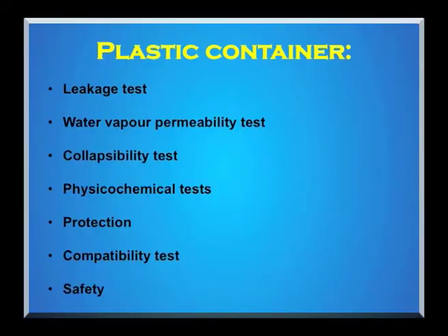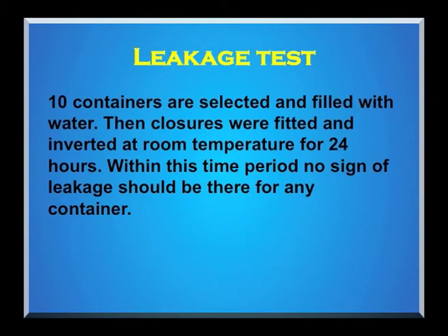Numerous tests are performed on plastic containers that include leakage test, water vapor permeability test, collapsibility test, physicochemical test, protection, compatibility test and safety test. Starting with the leakage test, 10 containers are selected and filled with water, then closures are fitted and the containers are inverted at room temperature for 24 hours. Within this time period, there should be no sign of leakage from any container.